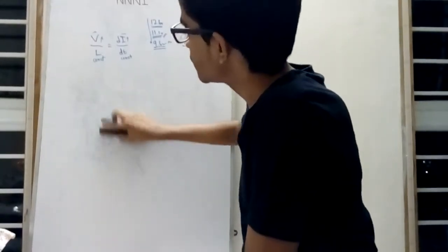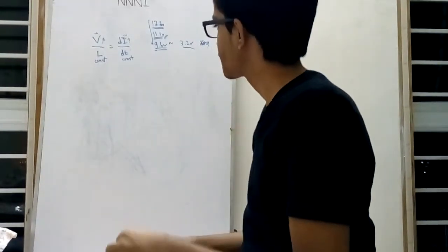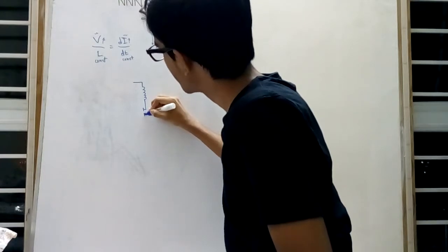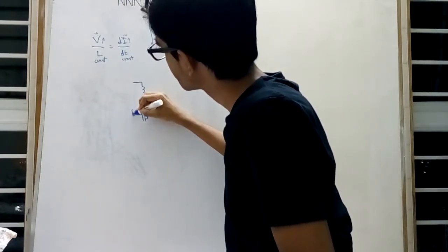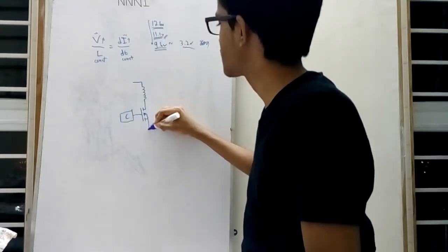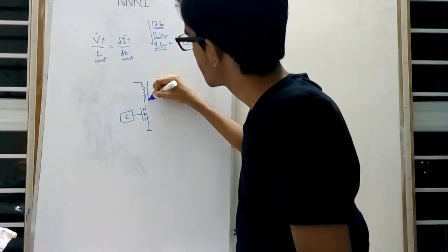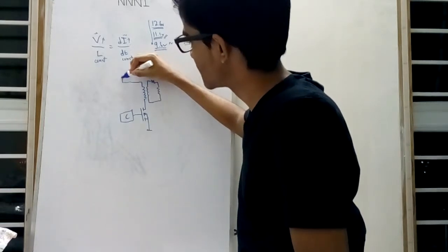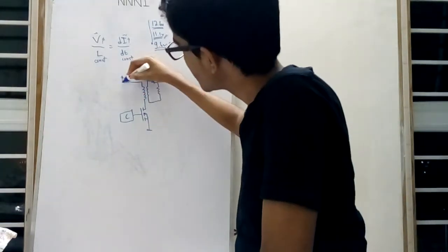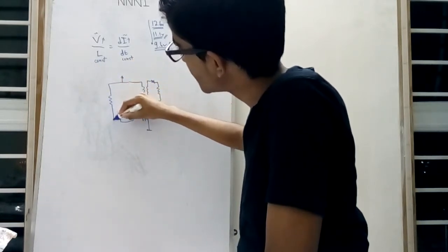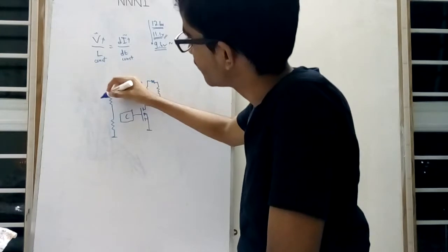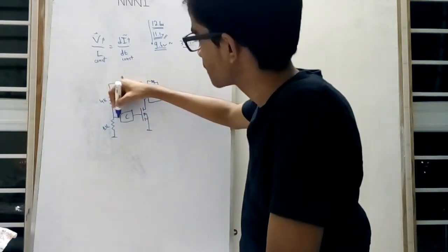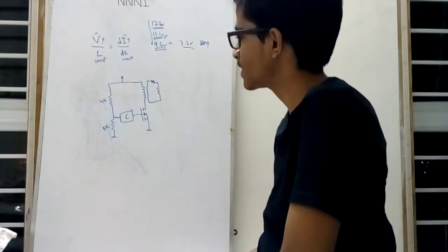Now the solution I came up with, sorry guys, involves a bit of programming. So we have the same circuit, practically everything is the same over here, except that I have eliminated the current shunt resistor, so the MOSFET is tied directly to ground. Secondary winding, and this is your power supply. So what I'm doing is I am setting up a voltage divider, 5x voltage divider. I'll tell you why later. 4K, and that becomes 1K. So you have a 5 times voltage divider feeding into this controller that controls the MOSFET.